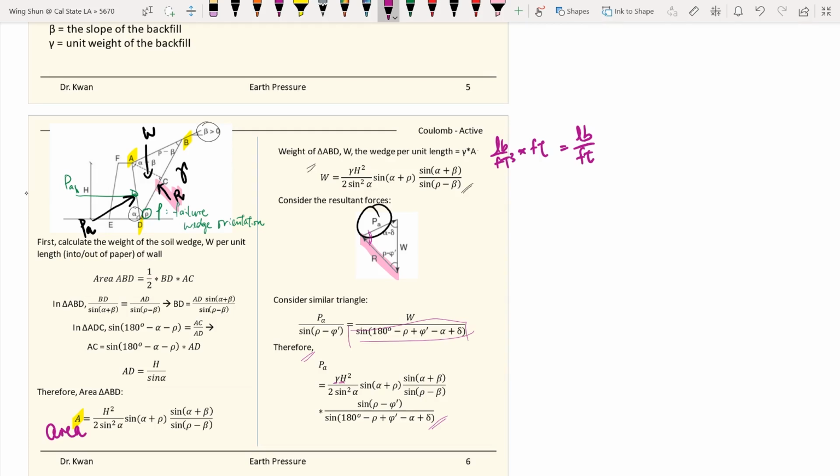And now, what is controllable in terms of analysis is the angle rho. So this angle here represents the orientation of the failure wedge. It really depends on the nature of the soils, and we can explain it in the system as the wedge that fails when the retaining wall is no longer able to sustain the loading behind it.